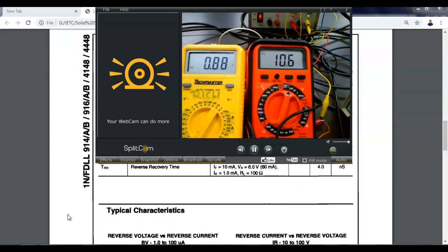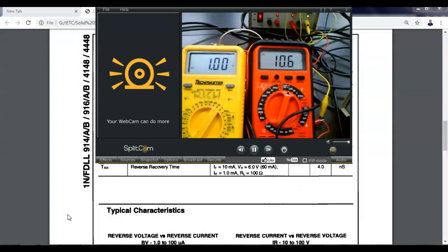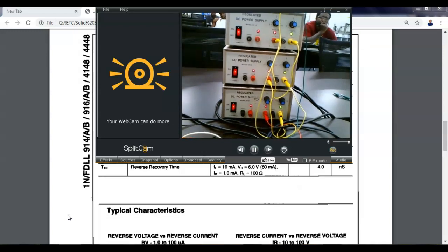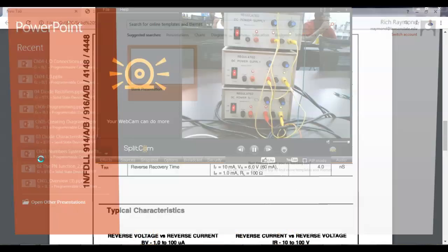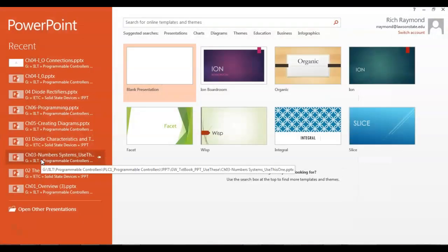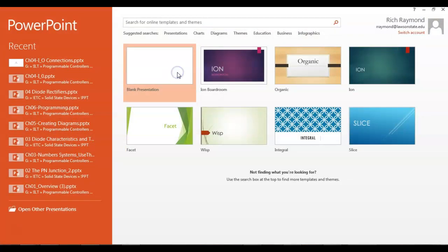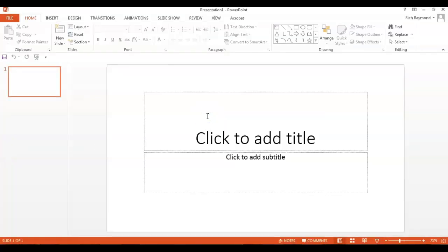Okay. So we're going to start off the first one, and I've got all these power supplies hooked up in series aiding. Y'all understand that? Yes or no? This is something y'all should have learned in DC. So series aiding means we take the positive of one and connect it to the negative of the other. So I have 4 variable power supplies. I've got them hooked up series aiding.